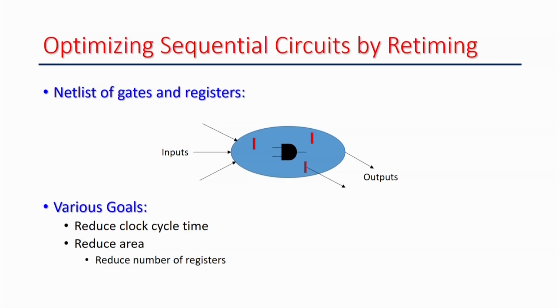Specifically, we are going to show how to formulate the retiming problem, and how to solve it algorithmically. So both aspects we are going to discuss today. As you have seen, a circuit consists of a set of registers and combinational units like gates, multiplexers, demultiplexers, and all those things, right. And our objective is always to improve either timing or area, right.